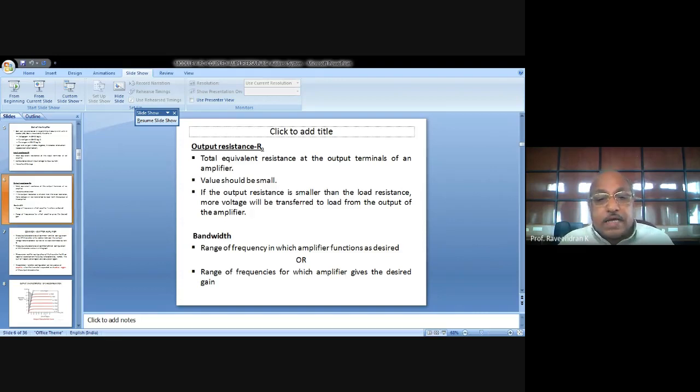What does it mean? It means that if you give an AC voltage here, alternating voltage with positive and negative half cycles, then with the same positive and negative half cycle variations occurring here, the output voltage will be an amplified version with a larger amplitude, but it is inverted. Inverted means it is in phase but with opposition, with opposition of 180 electrical degrees.